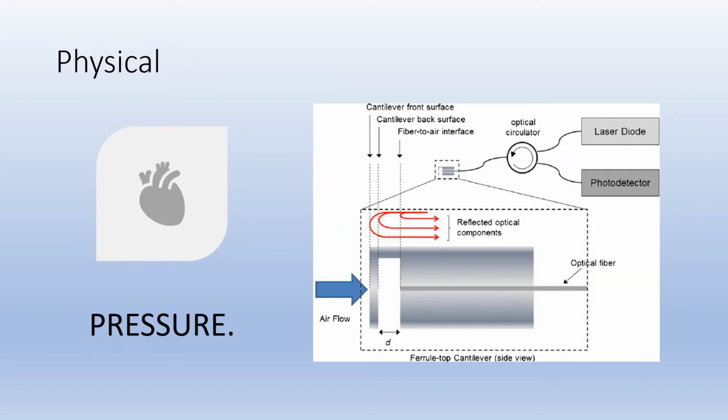A pressure fiber sensor works by using a cantilever mirror. This one is attached to a membrane located on the side of a probe. This causes light emitted from a central optical fiber to be reflected differentially toward either of two light collecting fibers on each side of the central fiber, just as shown in this picture.